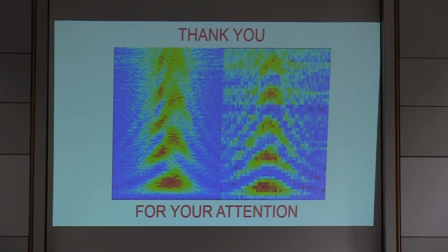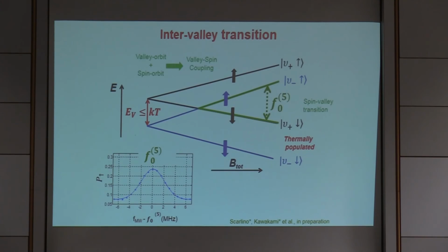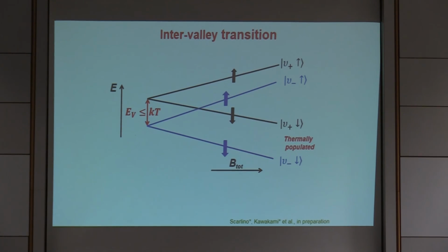Yes. So your valleys are split by the strain, and this depends on the composition of the silicon germanium layers. How much you can actually exploit these strain effects: the first splitting of the valleys, from 6-fold degeneracy to 4 and 2, is due to strain in plane. Then to split the further 2-fold degeneracy, you need to lift the symmetry along the z direction. You do this by breaking the symmetry, so building a quantum well, or introducing an electric field.